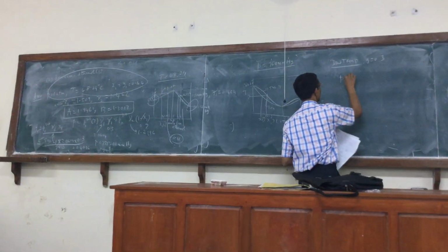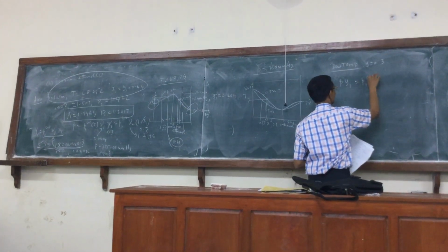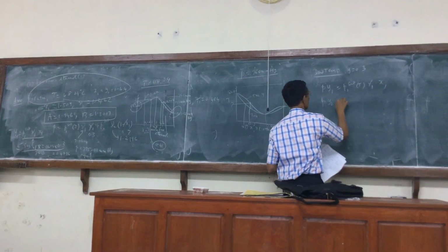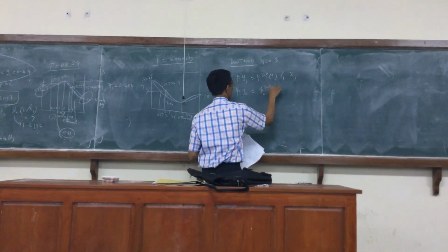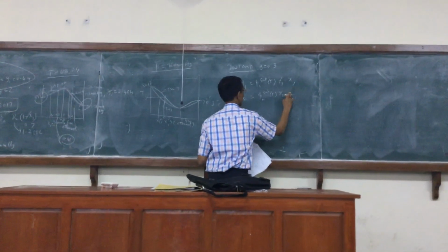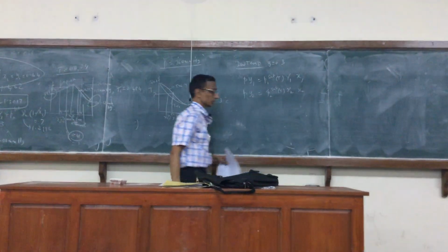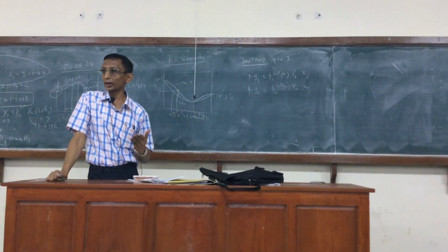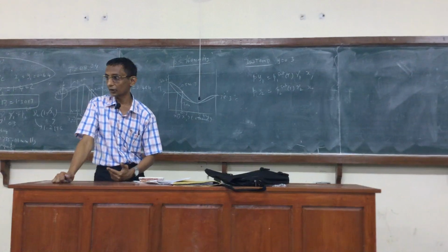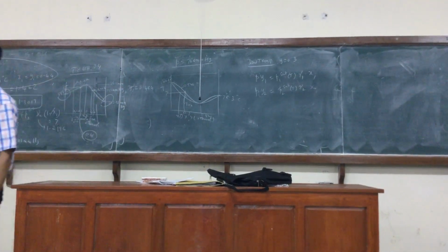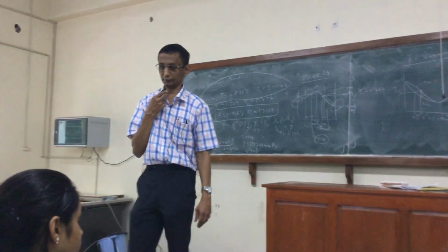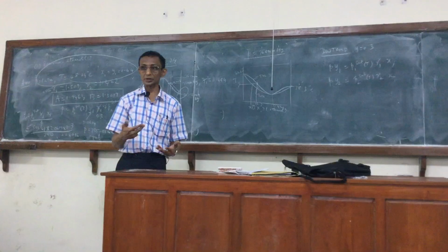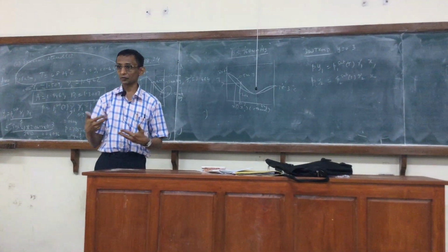So here we have again the idea: y1 P = P1 sat(T) gamma1 x1, and y2 P = P2 sat(T) gamma2 x2, where x2 is 1 minus x1. Right, so standard to say y is given. So I have to impose a mole fraction constraint for x. This is one of those algorithms from Smith and Van Ness, right? And then divide by one of the saturation pressures to get an iterative equation for the temperature.